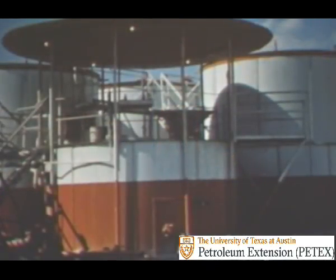Several mixing pits at the plant, depending on the quantity of oil mud needed, are made ready to receive the oil. This tank holds high flash point diesel fuel. The diesel is piped from this tank to the mixing tanks. Crude oil could be used, but diesel is preferred to minimize the fire hazard from volatile components that may be in crude.